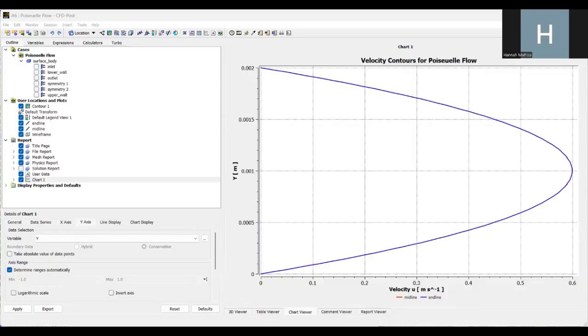And for the hybrid, I used inlet velocity of 0.05 meters per second, and the velocity of the upper wall is 0.02 meters per second. Then at the end, I exported my data, and put the graphs into my lab report, and I made sure to get 5 values for the maximum velocity and their heights. And then I solved for the Reynolds number for developing region and the laminar flow assumption.